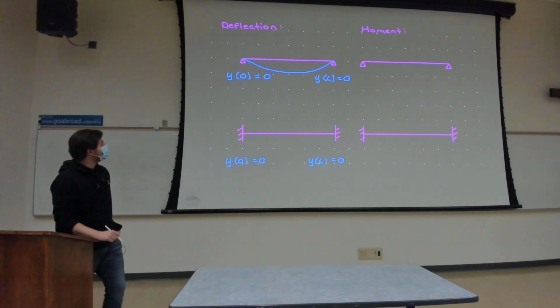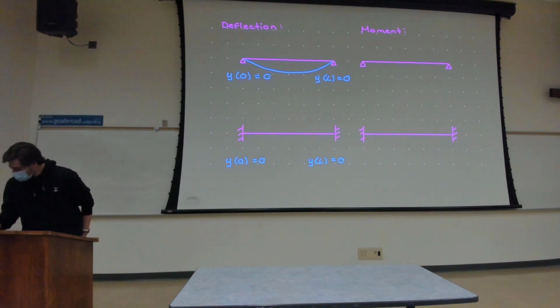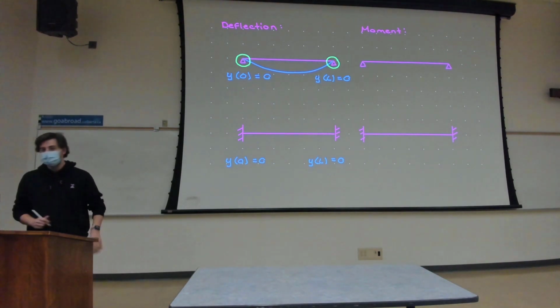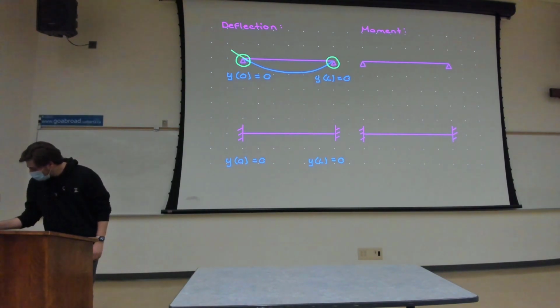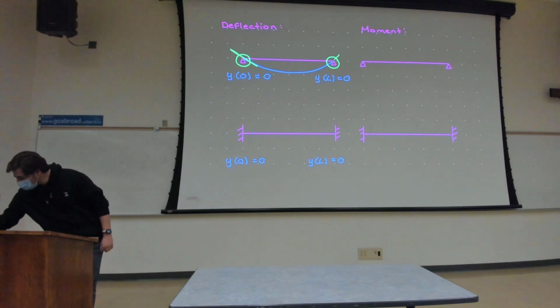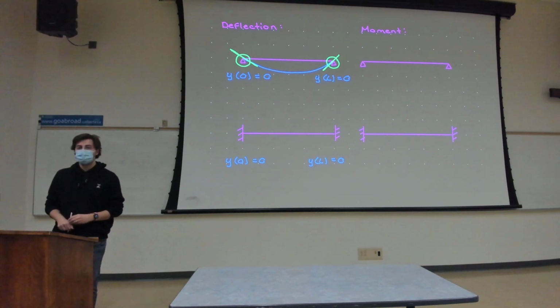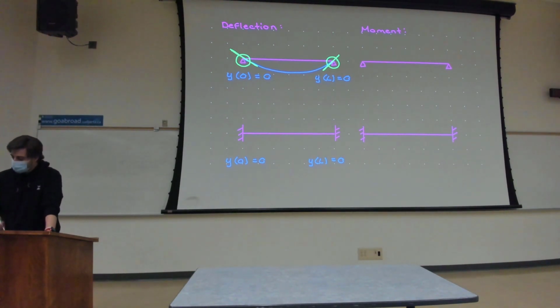So if we look at these two boundaries, I have 2 pins. Is my rotation at these 2 pins 0? No. As we can see, there is that slope downwards and then that slope upwards. But if we were to draw the moment diagram, what would it look like for a simply supported beam? Don't make me get the Eng 130 lecture videos out. I'll do it. Maybe the second pin's throwing you off. Simply supported.